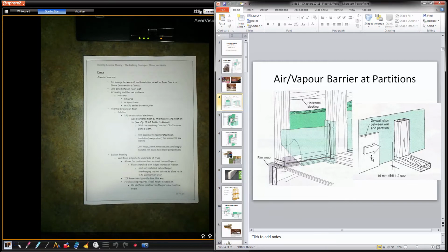But that would be something that you have to do if this was 1 unit of a multi-unit plex, and that's another unit of a multi-unit plex. Have drywall go through, maybe 2 layers of drywall to create a fire resistant wall.